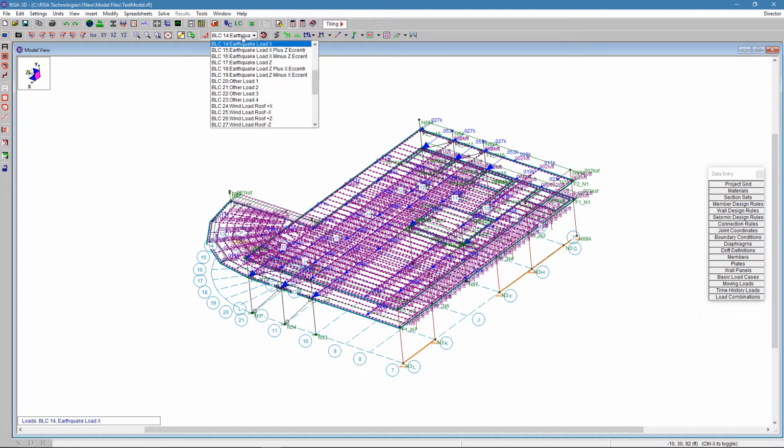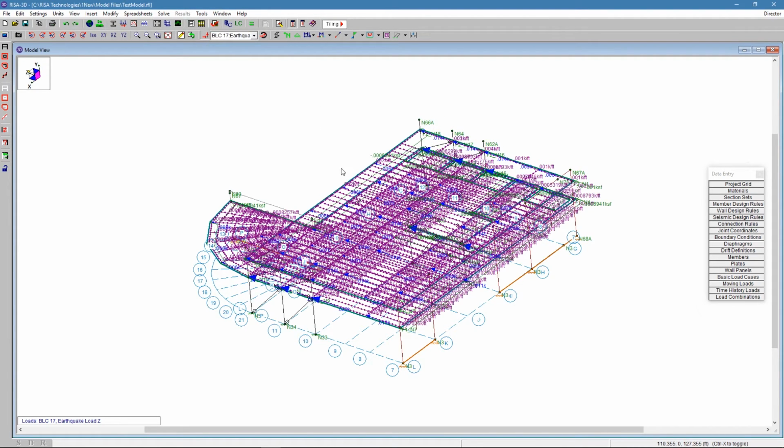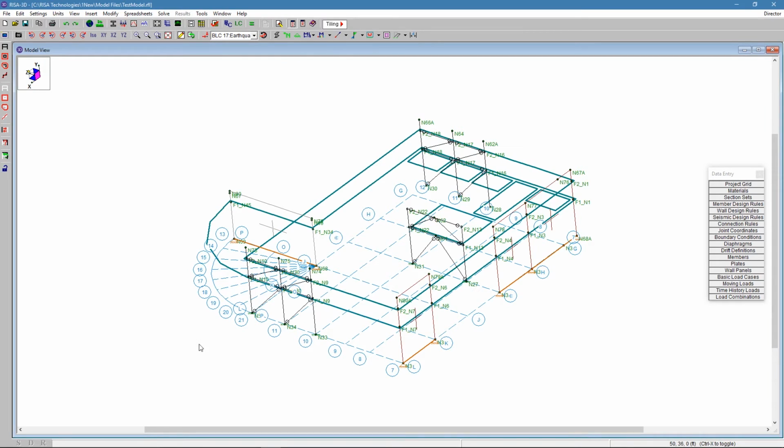So we apply the wind loads and the earthquake loads in the X direction and the Z direction, and you can see that they're smeared all in each portion there. A portion of the column weight goes into that. Everything gets kind of attached to its closest element there. So you've got loading all in there.